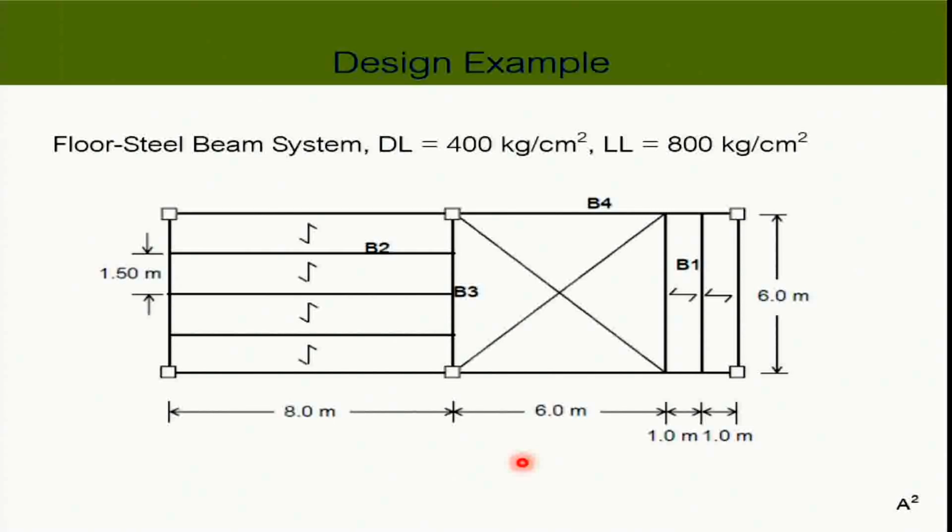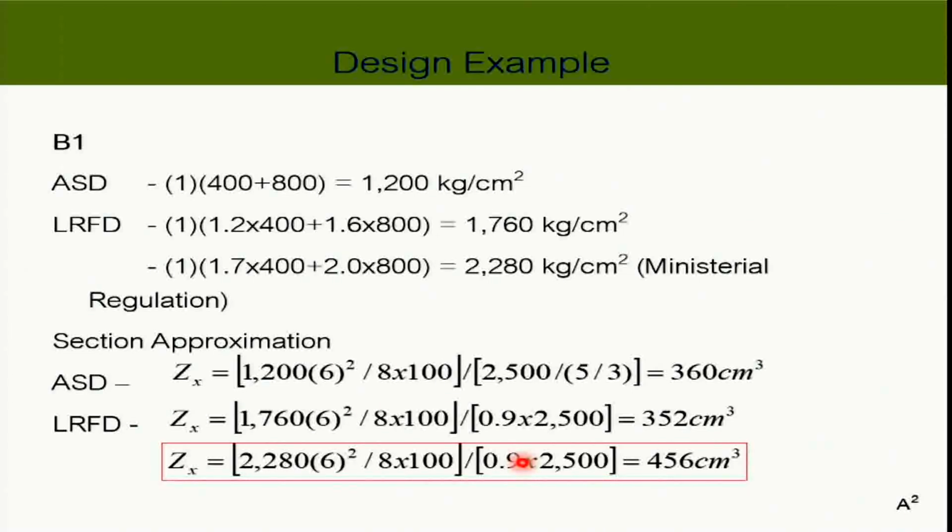All right. Now it means that when I want to design B1 and B2, I can just calculate the moment and calculate the plastic section modulus right away, because they will reach Mp without a doubt. Okay, so I make the case to compare ASD and LRFD, but you will see that you're going to get pretty much the same section here.